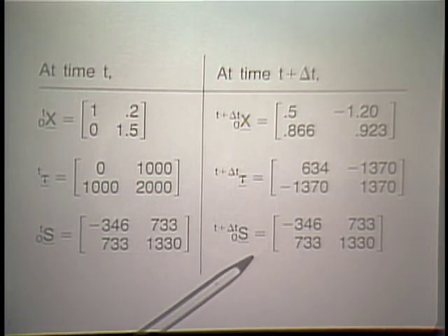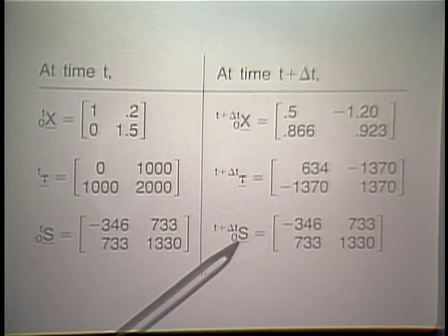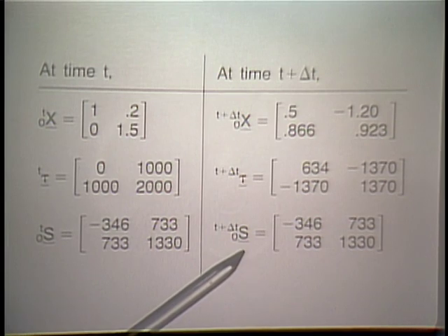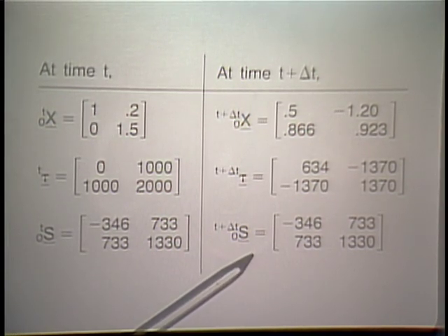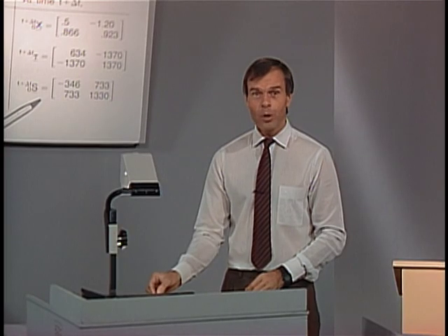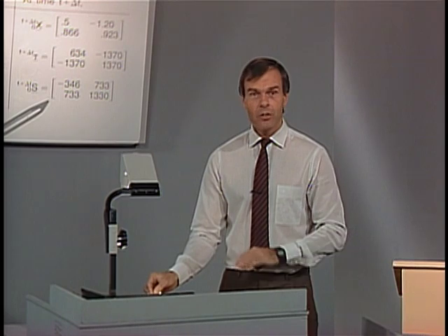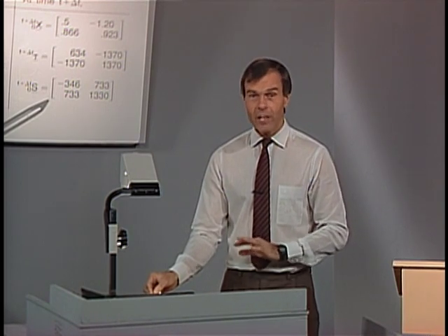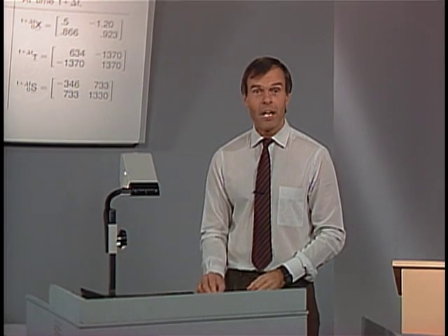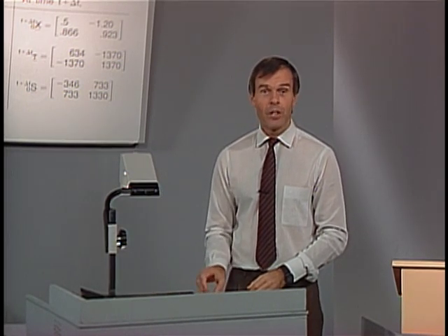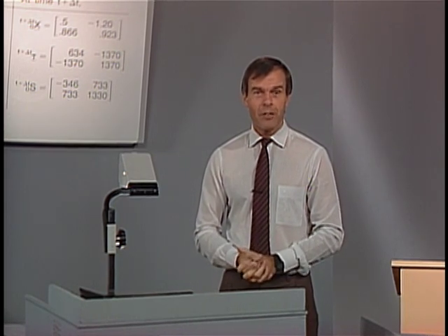One can, of course, prove that the second Piola-Kirchhoff stress tensor does not change when the material is only subjected to a rigid body motion, and such a proof is actually given in the textbook. But this is a simple application, and it exemplifies what I mean by that statement. It's an important statement that you should keep in mind as we go along with our further discussion of the mathematical basis of nonlinear finite element methods.